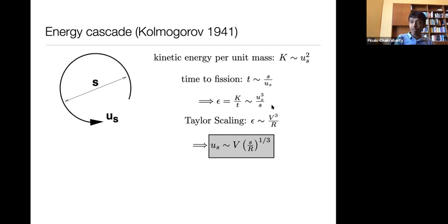So if I take this large scale setting of epsilon and I equate it to any arbitrary scale S, then by equating the two, I arrive at this very simple scaling relation that tells us how the velocity of an eddy, U_S, scales with the size of the eddy, S. And we get a power law, 1/3 over here, and we'll see that this 1/3 is going to play a role in our analysis. Okay, so this is about an eddy's velocity at any level of the cascade.